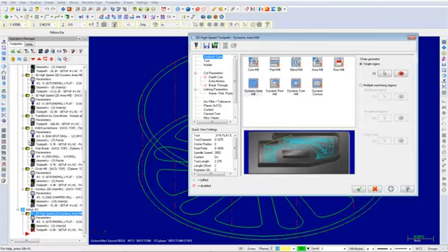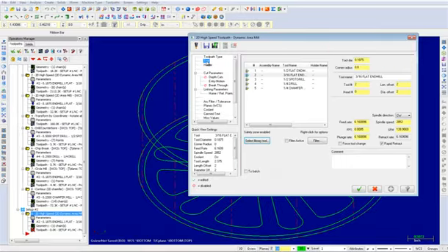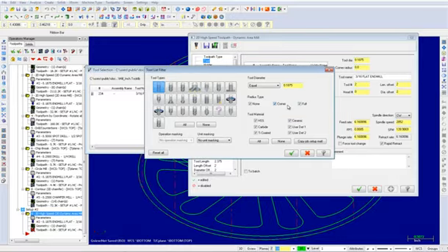In the Toolpath page, select the Dynamic Area Mill and then from the Tree View list, choose Tool. Now, click the Select Library Tool button and then choose Filter. Select the None button and then under Tool Types, choose the Flat End Mill icon.